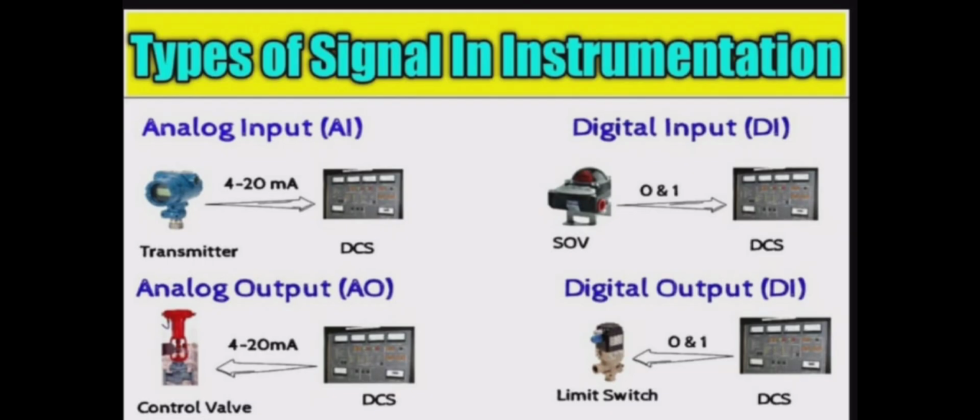First of all, I am showing you the digital input. The digital inputs are binary inputs. It's a summary, so be careful with it, and it is very important for your future. The digital inputs are binary inputs, that is 0 or 1, applied to the PLC. Binary inputs are basically voltages varying from 5 volt to 230 volt depending upon the type of card used. Different cards have different voltage capacity, varying from 5 volt to 230 volt. In simple words, any push button, switch or sensor produces the digital input to the PLC.